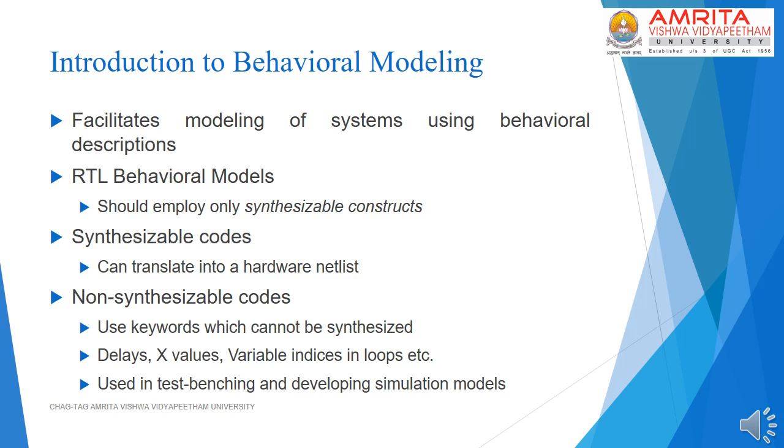Now we will move on to behavioral modeling. In fact, we will spend considerable time in this course trying to understand what behavioral modeling is all about. As I mentioned earlier, behavioral modeling lends hardware description languages their real power. In the behavioral level of abstraction, designers are able to model various digital subsystems based on their behavior. This spares the designer the painstaking task of trying to map the behavior of a digital system into a set of Boolean equations and trying to implement them using a set of target gates.